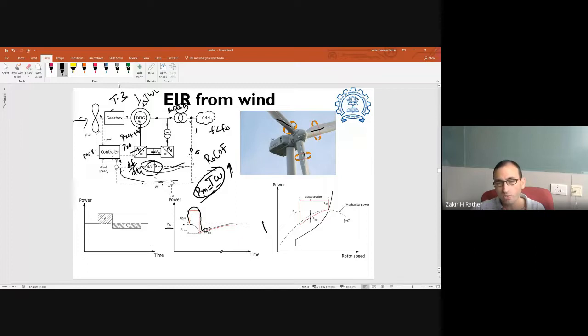And if you look, this is known as the power speed plot here, this is the maximum power point curve. And let us say it was operating at point A, and because of this inertial controller and disturbance in the frequency, it increases the power output to B suddenly. And it continues for some time. Why is it going reverse? Because the speed is decreasing for the reason I mentioned. It continues for some time till C, and then because of the controller, the speed hits its limit, which is normally 0.7 per unit, the machine now decreases its electrical power because it has to gain its speed.